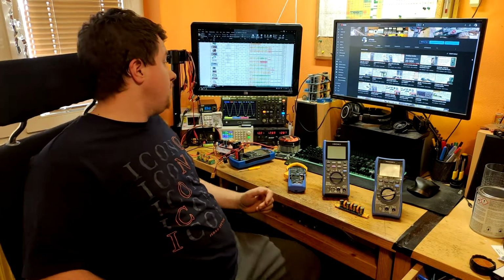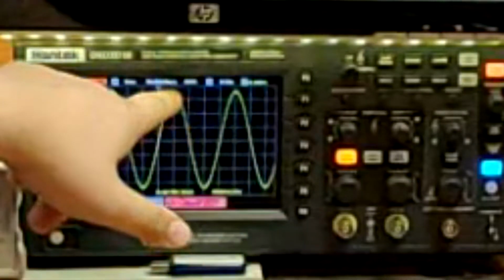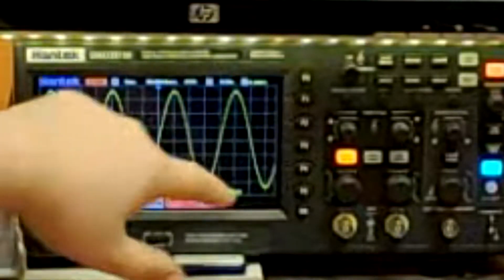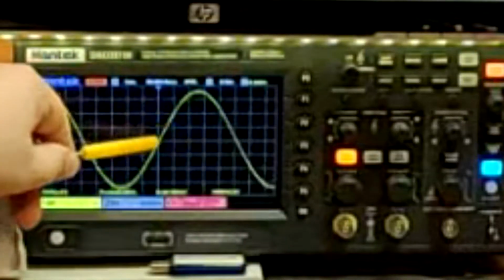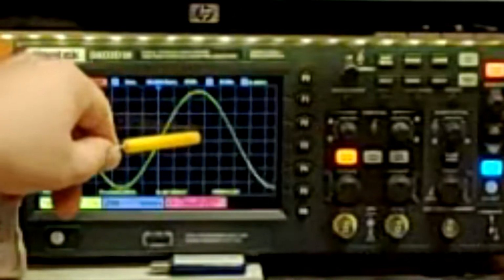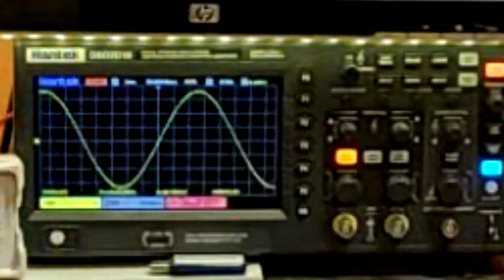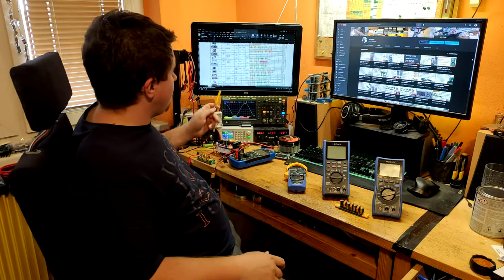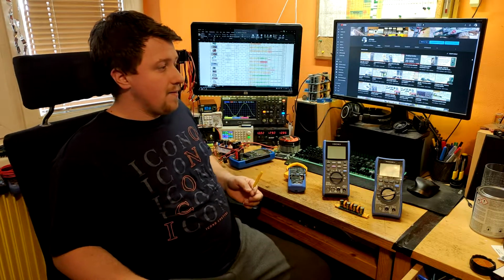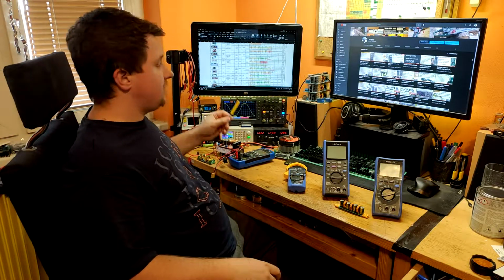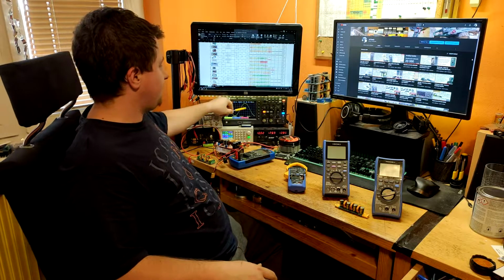For example, DC power supplies only take current when the sine wave of the voltage is at its peaks. So it only takes current in this area and in this area. That's all. For the rest of the time there is zero current, peak, zero current, peak. This is how your power supplies consume amperes. It's nowhere near sinusoidal. If you had a resistive load like a bulb or room heater, then the current would be perfectly the same as this voltage sine.